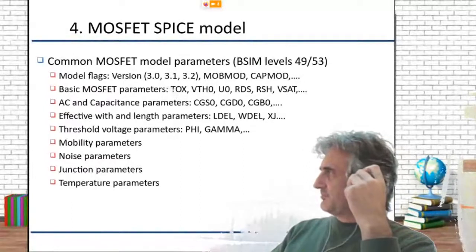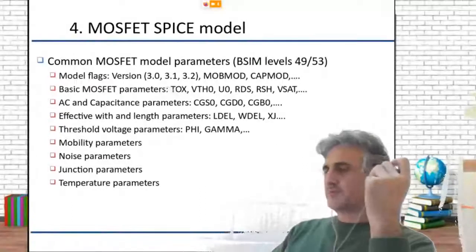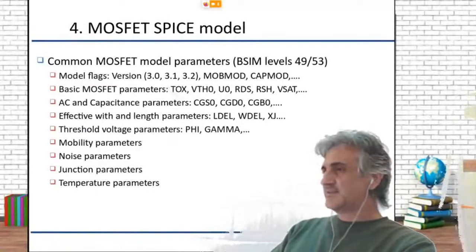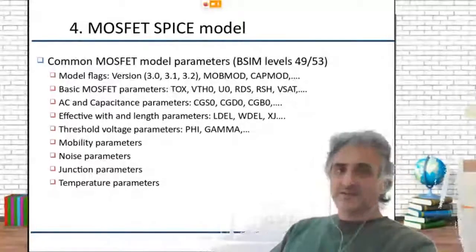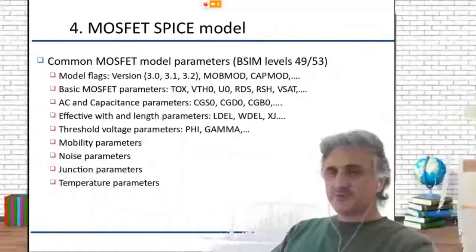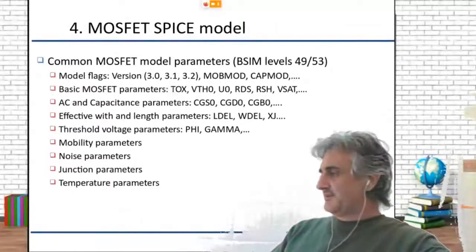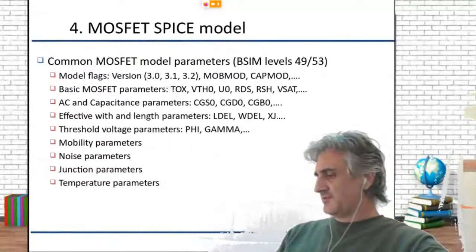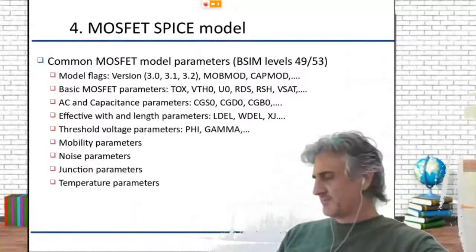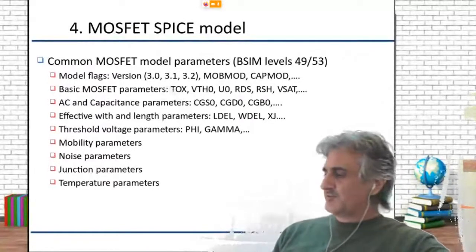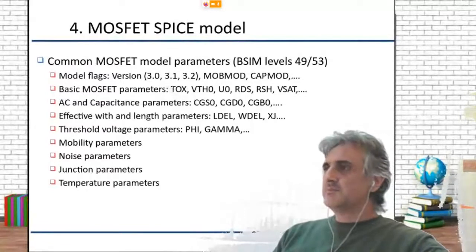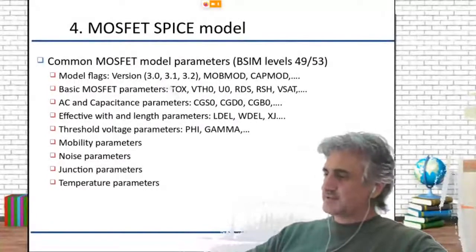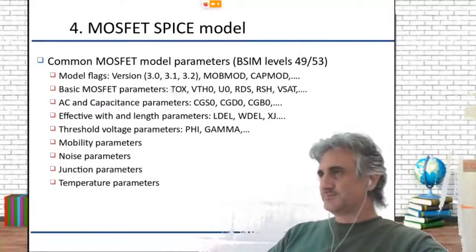Now the standard model is something called PSP11, which stands for Penn State Model Simulator, and it's also a mixture with something that they developed at the EPFL in Lausanne, in Switzerland, which is a mixture of two different models that behave more or less similarly. But never mind. However, the most known model is what is called BSIM, which stands for Berkeley Simulator.